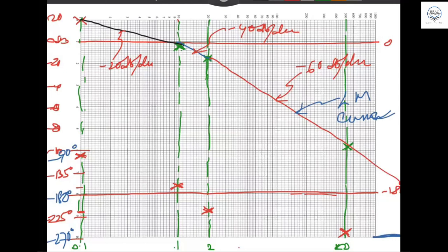So from minus 98, you can draw freehand like this, approximately. After getting like this, then jumping down and jumping down like that, to 0 like this. Just a freehand drawing, no need for a scale or anything in this case. So this is your phase angle curve. Okay, that's the phase angle curve done. The log magnitude curve and phase angle curve are completed. After drawing the phase angle curve, now it is the complete Bode plot. You have completed the Bode plot.